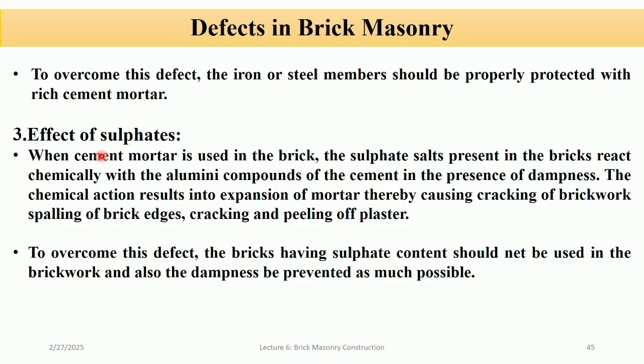So in order to overcome these defects, bricks having sulfates content should not be used in the brickwork, and also dampness should be prevented as much as possible.